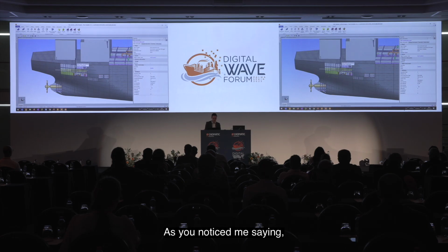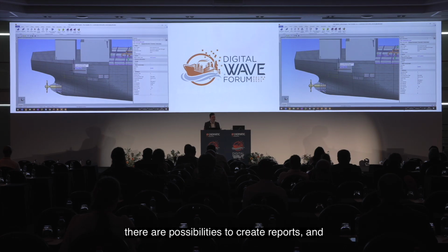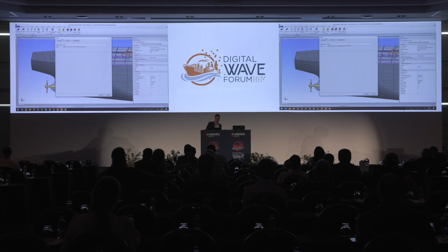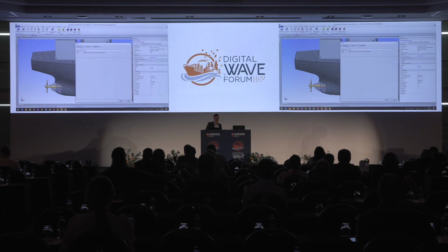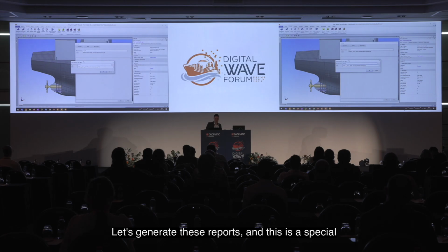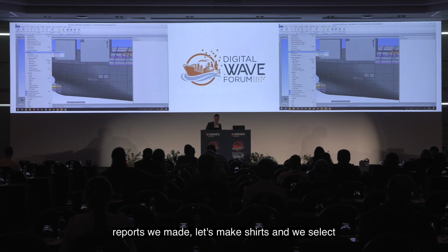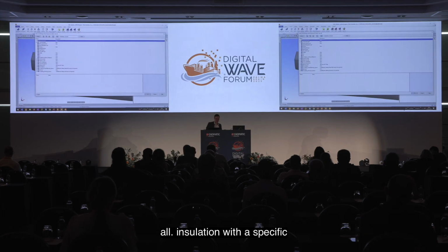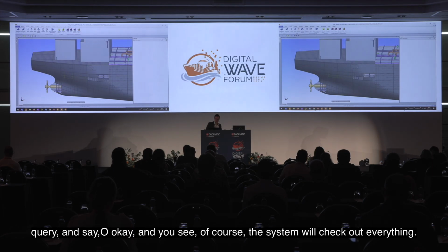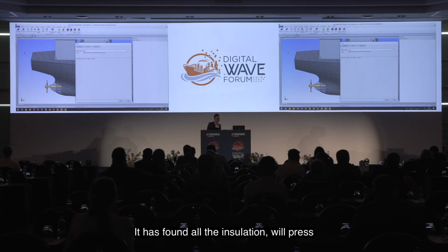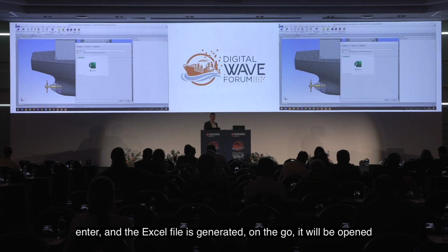As you noticed me saying, there are possibilities to create reports. And I created one that will show both hull and outfitting installation. Let's generate this report. And this is the special report we made. Let's make certain we select all installation with a specific query. And say OK, and you see, of course, the system will check out everything. It has found all the installation. We'll press Enter. And the Excel file is generated on the go.